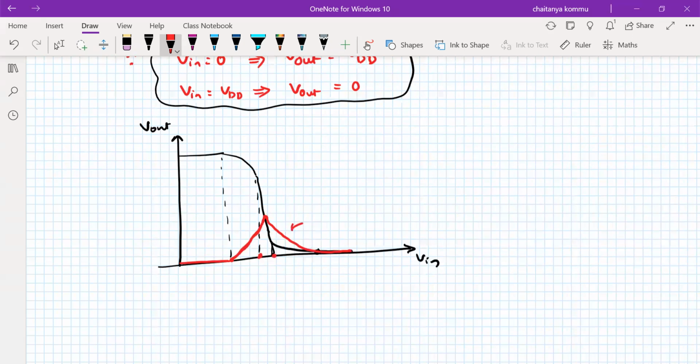So therefore, this is called the current characteristics in the CMOS inverter. The maximum current will flow when both the transistors are on, but we don't want to use this kind of scenario in our digital applications. We want to operate it at either high voltages or low voltages.